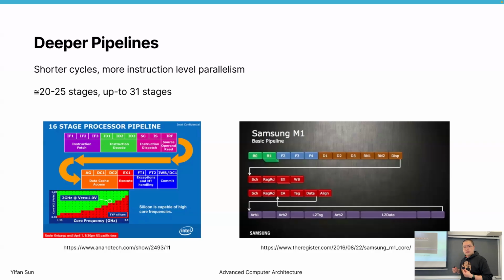But when a huge, massive workload comes in, it will transition to the performance core. An efficient core can have like 5 or 6 stages, and may not use the optimizations that we'll introduce in the rest of today's lecture, but the performance core will definitely go towards a super deep and super wide pipeline. Okay.